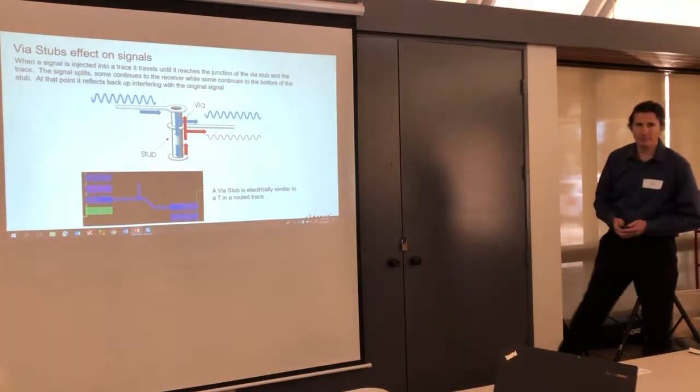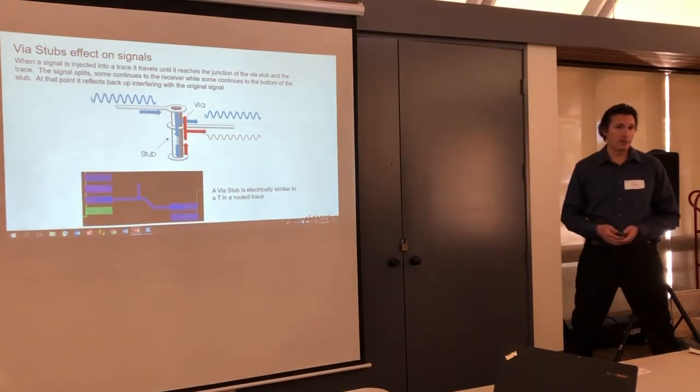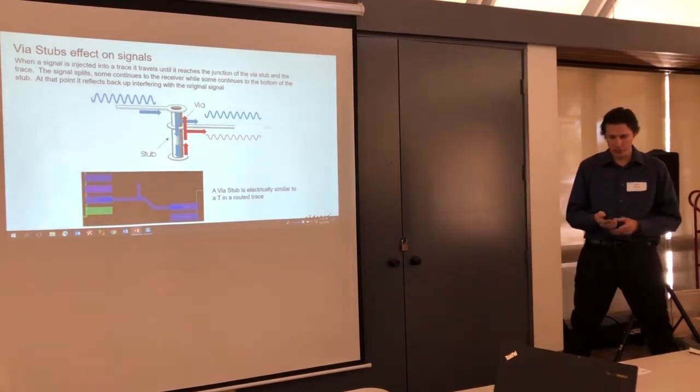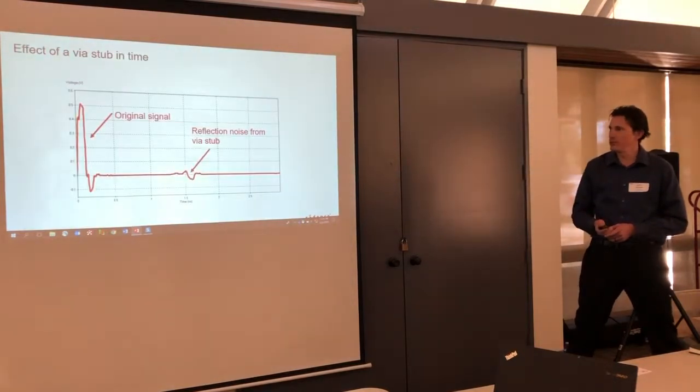Yeah, but if you're already using microvias, why would you back drill? Right, if you're already using microvias, probably not, right? There may be other manufacturing considerations that would come into play, but yeah, if you can get away with a microvia, then back-drilling is not going to really buy anything. So you're effectively doing the same thing. And if your signal has to go down to deeper layers, well, that would be a different thing. Right, yeah, if you can just go between the exact same layers, you're doing the same thing.